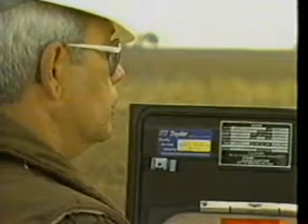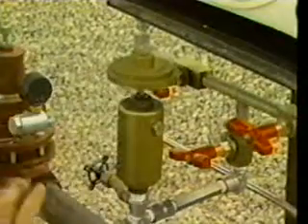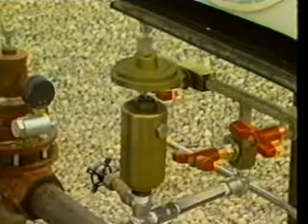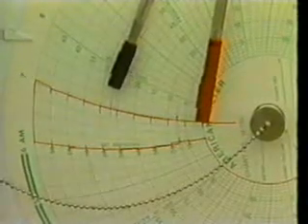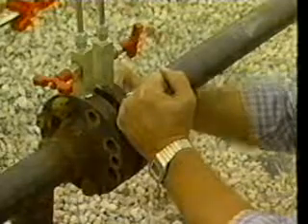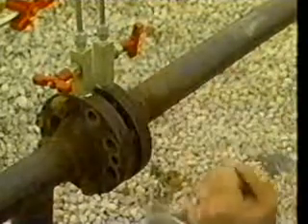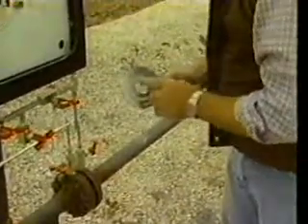Check the temperature recorder. Using the dead weight tester, check the static element for 0 according to contract requirements. Also check the differential element for accuracy and arc. Making sure that the orifice meter has been isolated and depressurized, then pull and inspect the orifice plate. With a senior orifice fitting, the isolation would not be necessary, but instructions for pulling the orifice plate should carefully be followed.